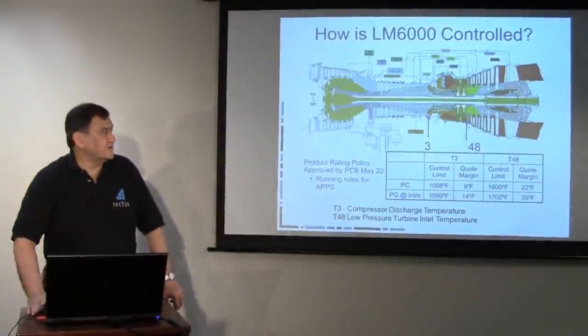And we talked earlier about how you need to understand if the turbine is being run just in that mode by its local computer system, because it will not give you any governing response. If that is the primary goal of the control algorithm, which is to generate megawatts, which is to make money, then you also have to be cognizant of the types of control modes that these computers are actually following, and work with your plant operators to make sure that there's a balance between having enough turbines around that can give you the governing response versus just running them at the full output.